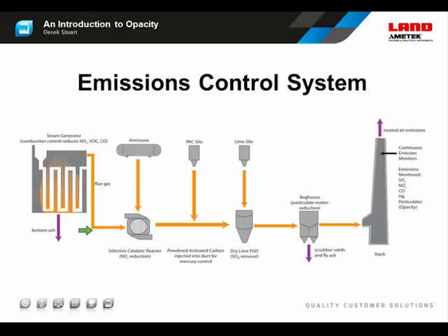The flue gases contain a lot of pollutants, and on a modern power plant, these can largely be removed. So the first phase is typically removing NOx, NO and NO2, and this is done by a process called selective catalytic reduction, SCR, where the flue gases are mixed with ammonia in the presence of a catalyst, and this converts the NOx to water vapor and nitrogen. This has to be done at a high temperature, which is why it's the first process in the flue gas cleanup.